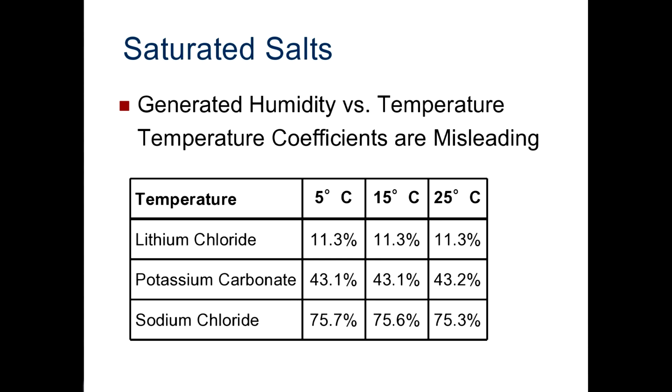Now, I've shown here the humidity generated as a function of temperature. And, you know, that looks pretty good. And one might conclude that saturated salts are not temperature sensitive. But these temperature coefficients can be very misleading, because these numbers assume that the system is in thermal equilibrium.